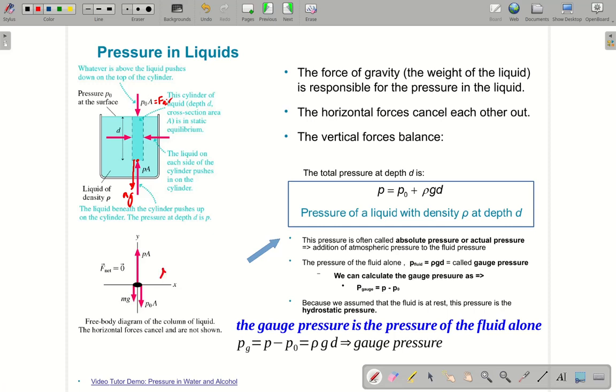And we can write down an equilibrium for that point. So upward forces, that would be the total pressure at that point times the area, is equal to downward forces, mg, plus the force by the atmosphere. That would be the pressure of the atmosphere times the area. Again, this comes about by the fact that F air here would be the pressure of the air. We will always call the pressure of the air, or air pressure, P0 in this context, divided by the area it applies. The area I'm talking about will be the area of interest here.